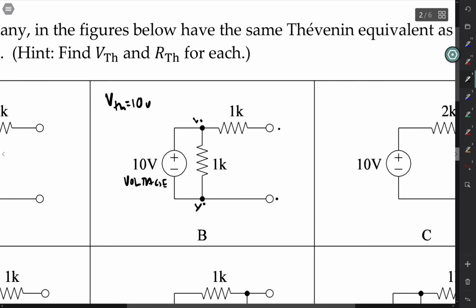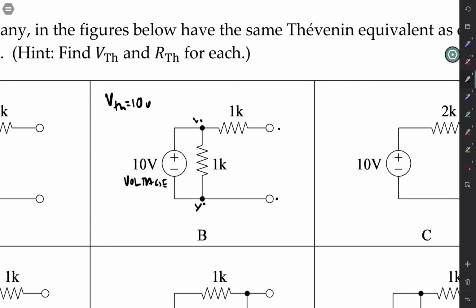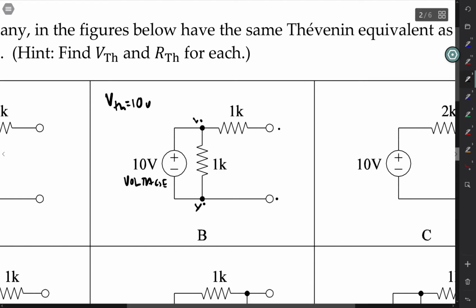On the other hand, the Thevenin resistance is basically going to be the resistance that one would see looking back from the output through the resistors back through the other terminal. And because this voltage source right here is in parallel with this resistance right here, the resistance itself does not matter because the voltage is maintained to be the same between those 2 points. So in this case, the Thevenin resistance is also 1K, just this one resistor that is in series.